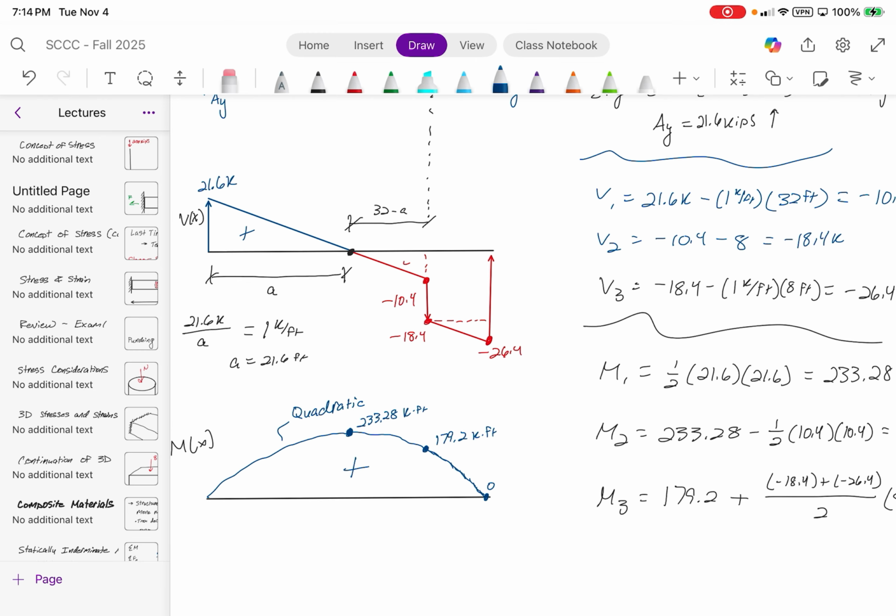Column buckling is honestly an easy topic until you start adding more stuff to it. The thing with column buckling is understanding the boundary conditions for the problem. And then also understanding how, for example, this column right here, you might think it's just whatever the height from this floor to that floor is, but it's not as simple as that, because that column spans several floors. And then the size of the stuff changes as it goes up, right? Yep, and then accounting for the stiffnesses of the beams too, which we don't really get into. I give you guys very simplified models.